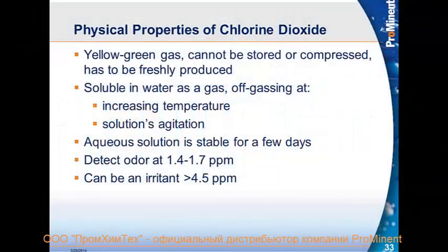To get started off with, chlorine dioxide is a gas. Don't let anyone fool you that it's a liquid, that there is such a thing as stabilized chlorine dioxide, because chlorine dioxide is anything but stable, at least in the gas form. However, it is very soluble in water, even more so than chlorine. It can off-gas depending on the concentration that it is created at, so you have to be aware of that.